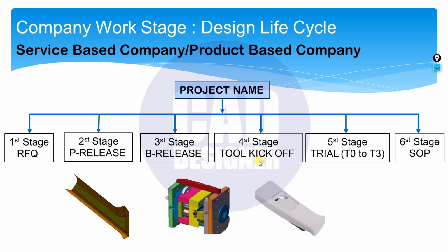Once the mold gets developed, it is assembled on the injection molding machine, and we get the part for the trial. This trial part comes under the fifth stage. The first sample we get with the new tool is called T0. Again we check this sample aesthetically for any plastic defects or design issues, and whether it assembles properly with its environment parts in the assembly or not.